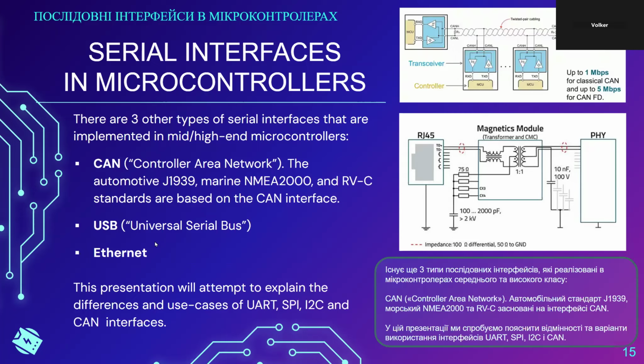There are USB repeaters, but interfaces like CAN, RS-485 or Ethernet can go 100 meters or longer, cable lengths that USB typically cannot do. Of course, if you need a connection to a PC for loading configuration data or retrieving log data, then a USB bus on a microcontroller is immensely useful.